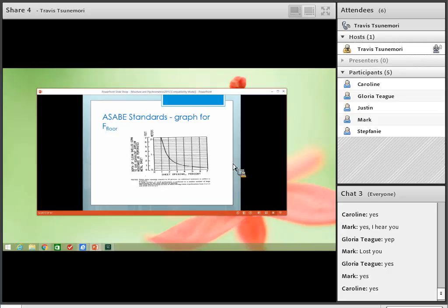So what this graph really tells us is if we didn't worry about the floor and we only treated it like grain, how much grain would that floor resistance add to the pile? And you can see from this graph that once you get above 7% opening in the floor, it really isn't a factor anymore. So it's really only when you have a really small percent opening in the floor that we worry about it.